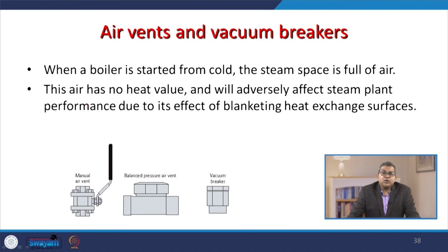There are certain air vents and vacuum breakers also equipped in the boiler, and the reason is quite obvious. When a boiler is started from cold, the steam space is full of air, and you know that this air does not carry any heat value.